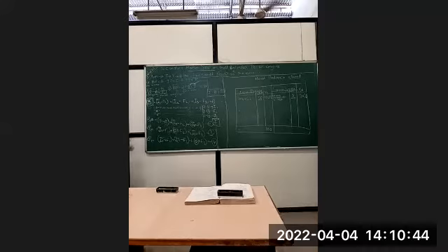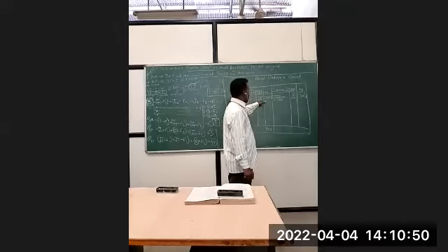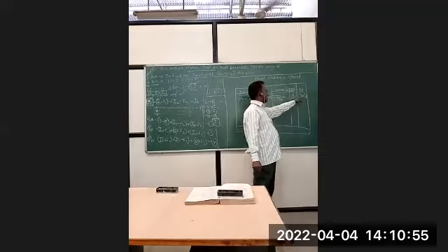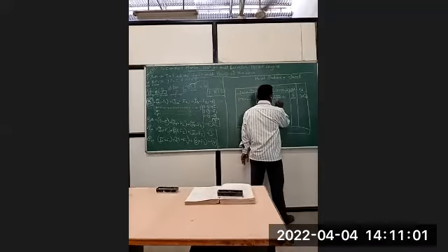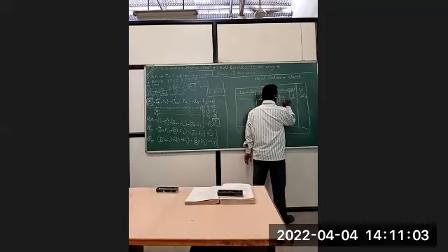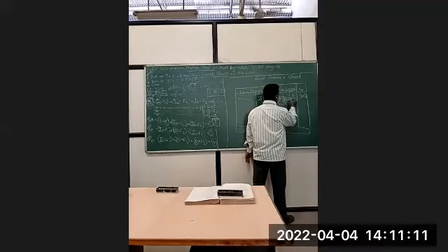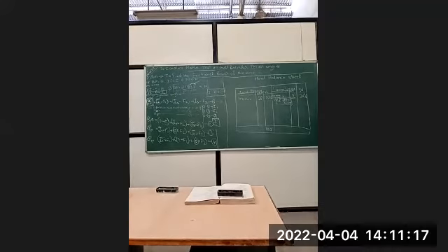So out of the X amount of energy that we have received in the engine, Y amount of energy, which corresponds to almost 30%, is being converted into power. Now, how to find this out? We have the equation BP is equal to 2 pi NT upon 60,000 kilowatt. So this equation we will be using to find out this percentage. So now out of the 100%, around 30% of the energy has been converted into power.